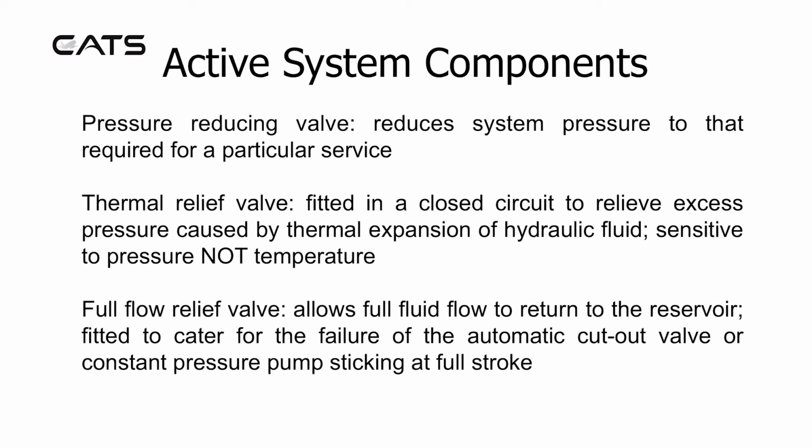Pressure reducing valves. These reduce system pressure to that required for a particular service. Thermal relief valve. This is fitted in a closed circuit to relieve excess pressure caused by thermal expansion of hydraulic fluid. It's sensitive to pressure, not temperature. Full flow relief valve. This allows full fluid flow to return to the reservoir. It's fitted to cater for the failure of the automatic cutoff valve or constant pressure pump sticking at full stroke.